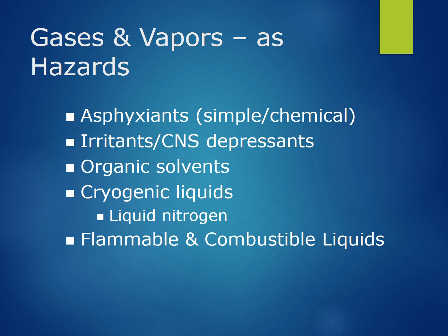The hazards associated with gases and vapors also vary, from asphyxiants, both simple and chemical, simple being that the chemical displaces oxygen in the lungs, similar to water displacing oxygen in a drowning victim, or chemical asphyxiants such as carbon monoxide, which replaces oxygen being carried by hemoglobin throughout our body.